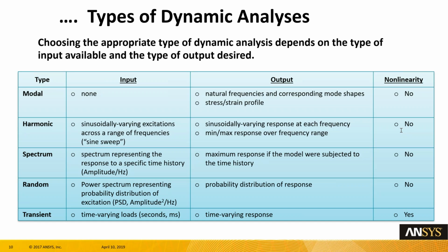So what's a good damping value that you can use if you don't know what the damping values are? We typically use anything from 1 to 3 to 5%, 5% being max. But typically 1 to 3% is a good damping value that can be used for metallic structures. Anything else may be too much.